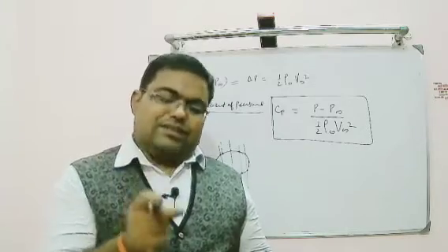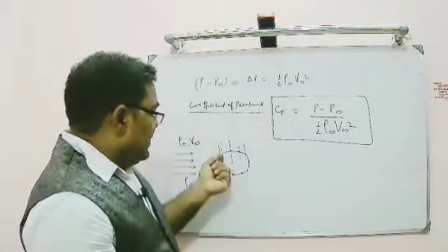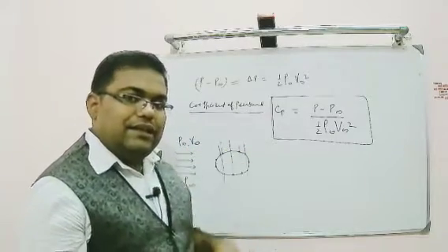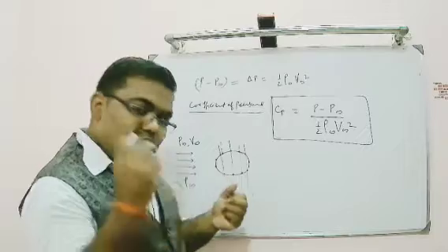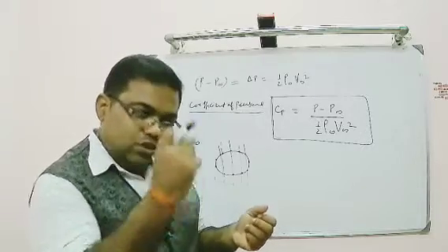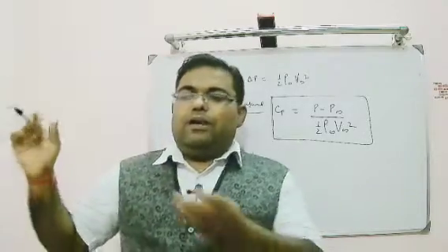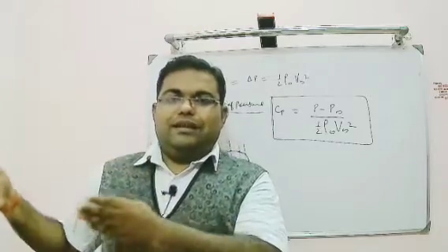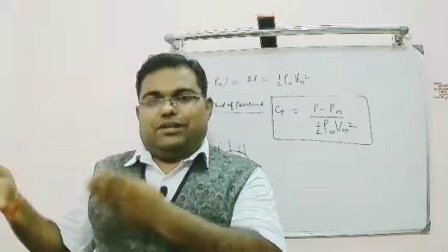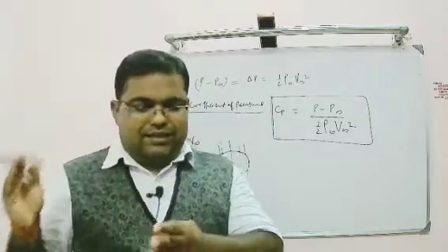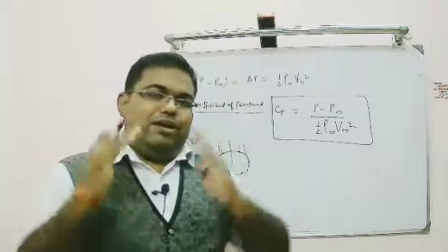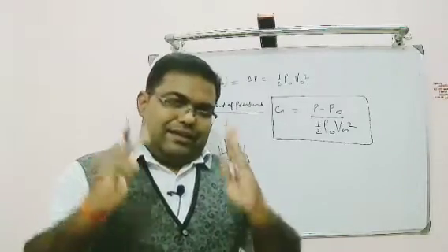Ports are nothing but a tube kind of structure that will suck the air. So when air is coming and it travels over the surface, through these ports, these holes, air will go inside, and that tubing will be connected to the multi-bank manometer. Each location we usually measure the pressure, and by taking atmospheric pressure as a reference, we find out the pressure coefficient at different locations.